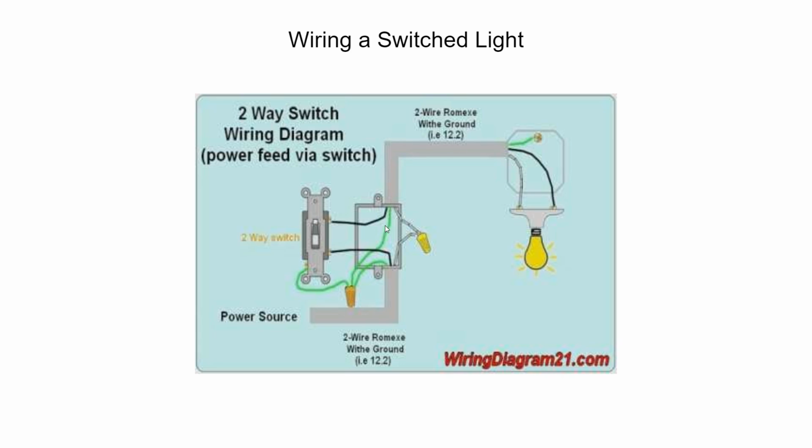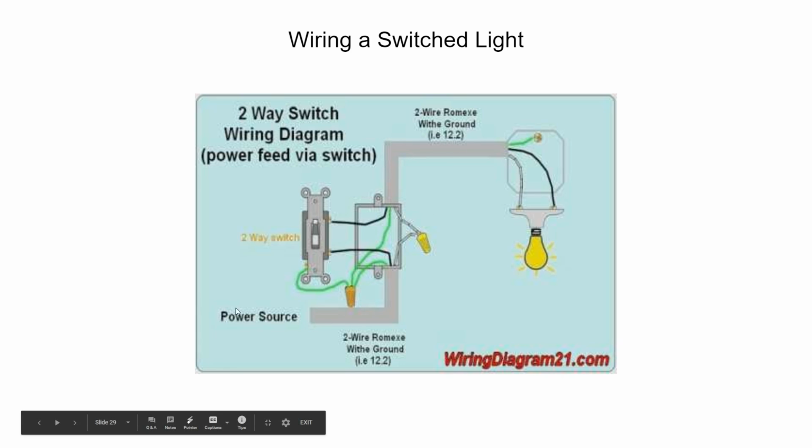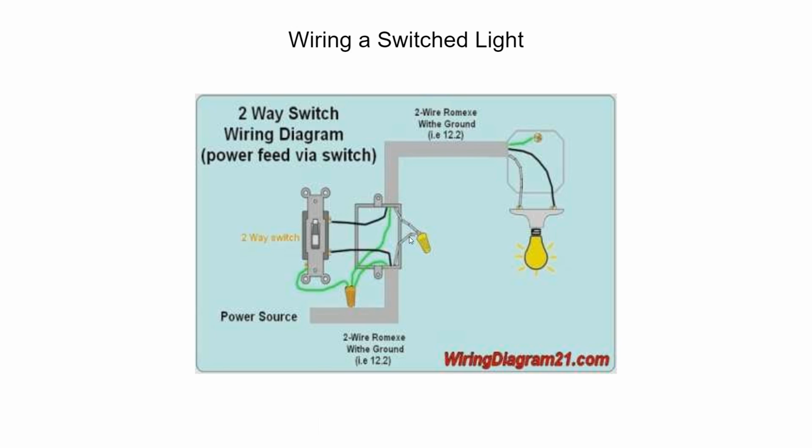This wire from the light and the white wire from the power source, they get connected here. The green wire needs to continue on, but it also needs to ground this switch. So we use a jumper to connect the switch, and then we wire nut those 3 wires together, and we carry it on. When you do this, you are stripping off wire up until the box.